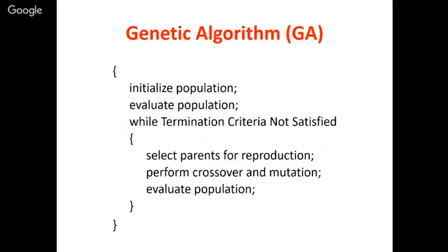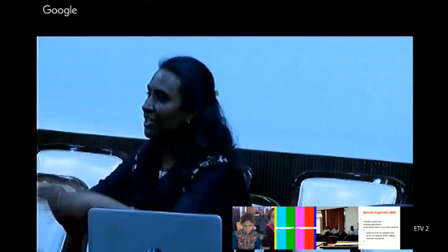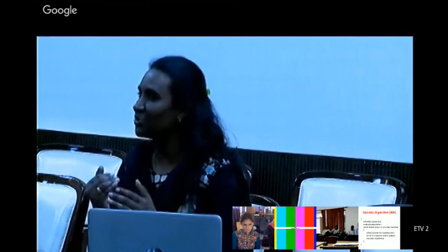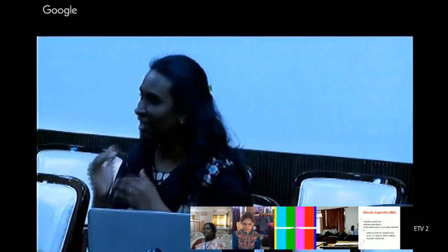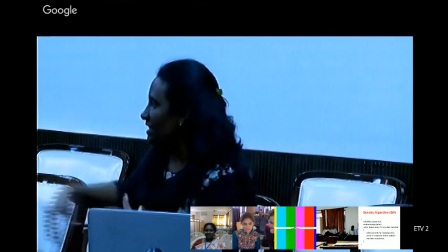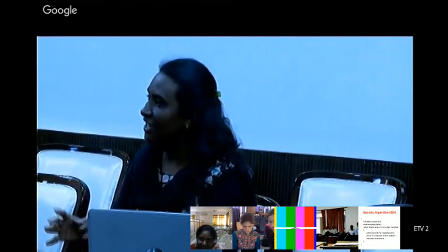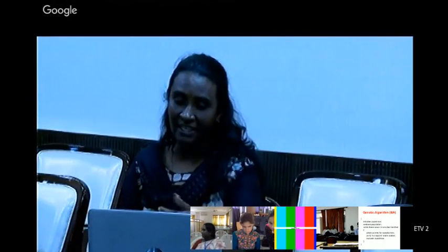First, we take the population, we evaluate it by putting it inside a fitness function, which is our THD equation. So all these answers we put in the THD, we see whether the THD is minimum or not. Okay, so that is the first step we do. It should be below 5, say we got 6. So again we have not reached. So what do we do? This is the parent. From these parents we produce their children, and those children again move towards the solution.